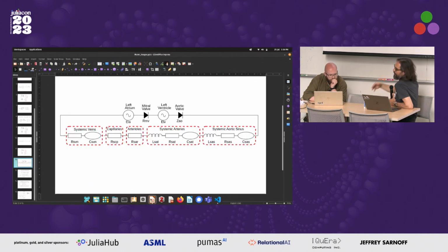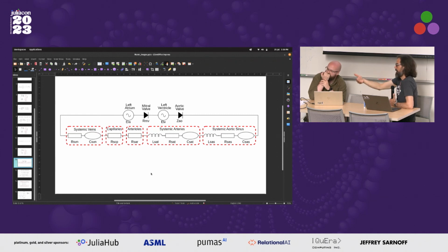Or an increase in the resistance that goes up with time. You define the resistor not with a fixed R parameter, but with R equals function name, then hand over the function name to that element and define the function externally. That would be the easiest way to do it.